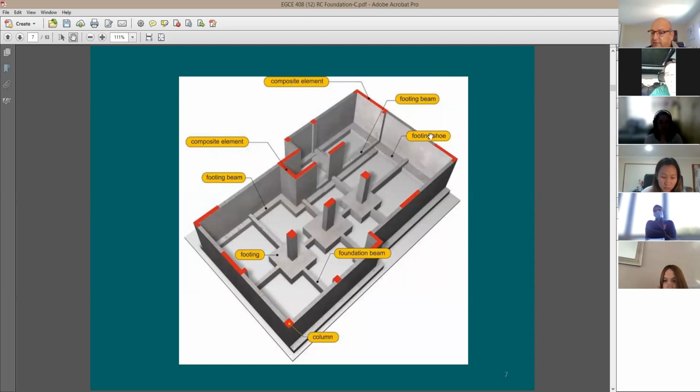Another 3D picture for the columns, and this is going to be through the pavement again. And look here, here is a pad, right? Understand that this pad is going to be transferring the vertical pressure coming from the column to the pad to the soil. Now the question is, what do we have?